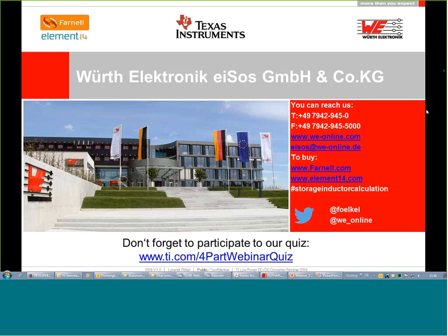In my experience, every time when the pick and place machine was not fixed to put the inductor in the right direction, some of the DC-DC converters at maximum load, or even at half load or not so high load, started to make an audio noise, a very high frequency audio noise. Then we soldered the inductance turned 180 degrees, soldered back, and it was gone.